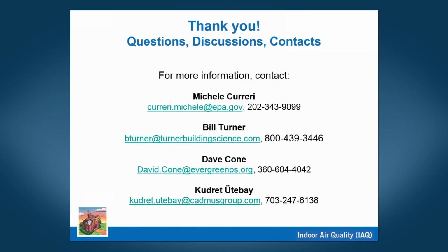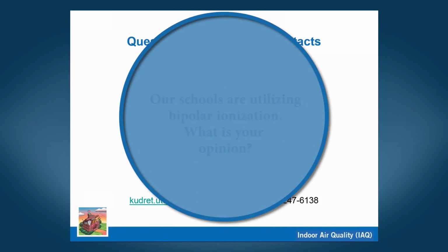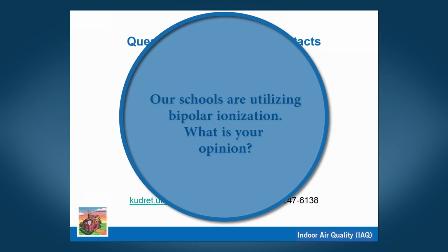Great. Thank you so much, Dave. All right. The next one, Bill, I believe this comes over to you, but Dave, you may also have an opinion. Our schools are utilizing bipolar ionization. What is your opinion? Bill? I think it's important to understand if someone's using air ionization to accomplish particulate air cleaning, to make sure that under no circumstances is ozone being generated as a byproduct.